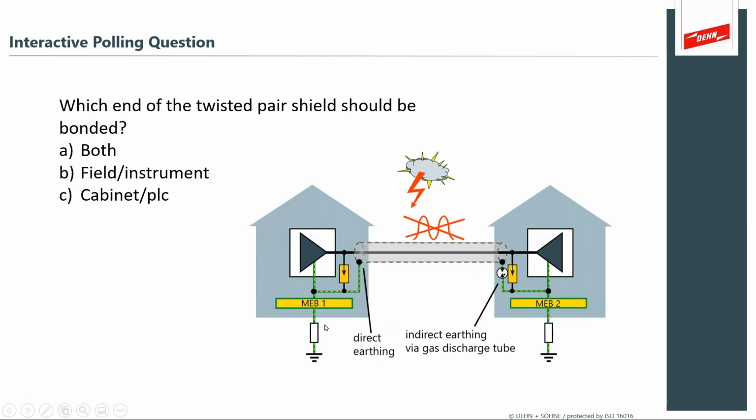But what's important about this is that you see that these structures could have substantially different earth electrodes. There could be a distance and a voltage across from these electrodes into the earth. The master bar at number 1 isn't necessarily the same master bar at number 2. And what's important here is that the shield should be maintained to reduce electromagnetic noise, but here we're allowing it to be bonded through a gas tube, indirect bonding. It's bonded momentarily when it sparks. And that's like that relief valve.